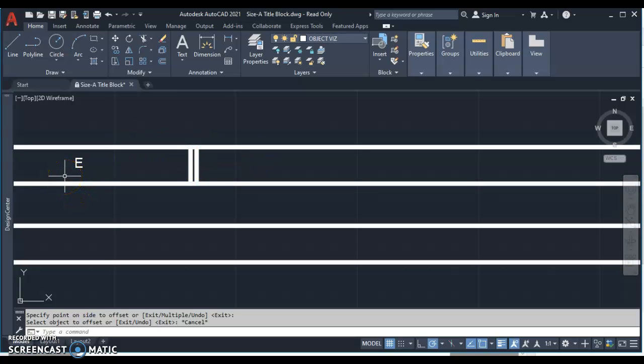So let's grab the line tool again. I'm going to mouse over here on the corner. There are a couple different ways of doing this. And I want to extend. I'm going to pull across here. I see my extension line. I'll type the number 4. Enter. And there I am 4 inches away. And I come up again. And I have my second 4 inch part. So I hit escape and get out of that.